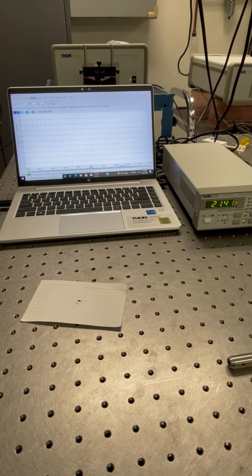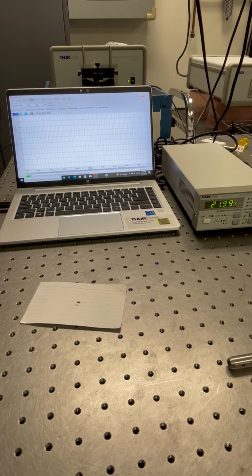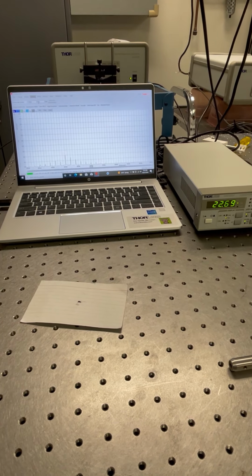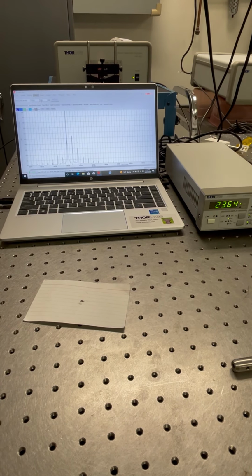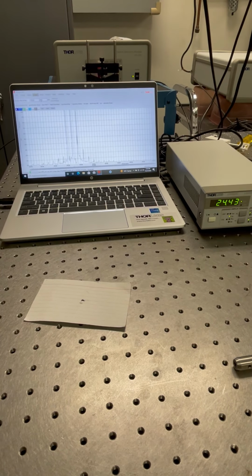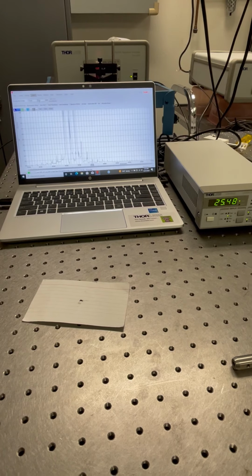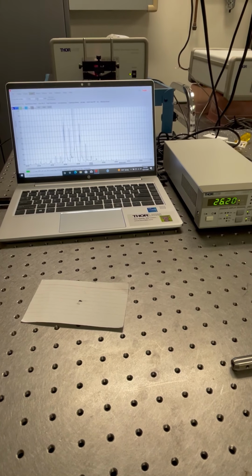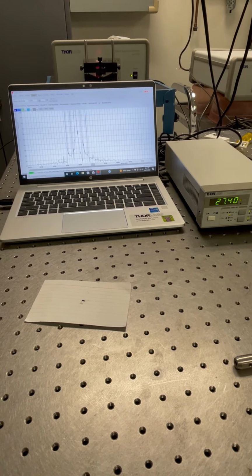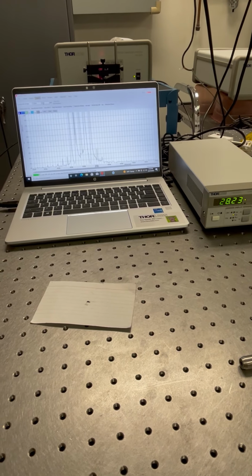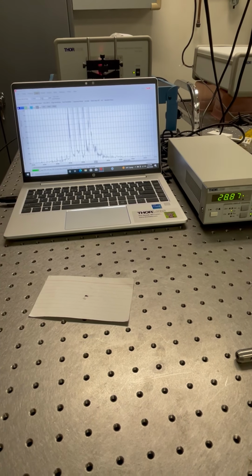Afterwards we used an optical spectrum analyzer to observe the spectrum of the laser diode as we changed the current. Below the threshold current we see pretty even peaks with no dominant peaks. At the threshold we get a dominant peak, and as we increase the current above the threshold we see a switching of dominant modes due to temperature effects.